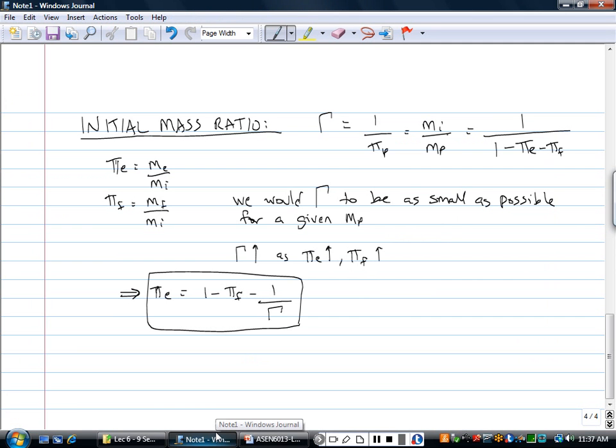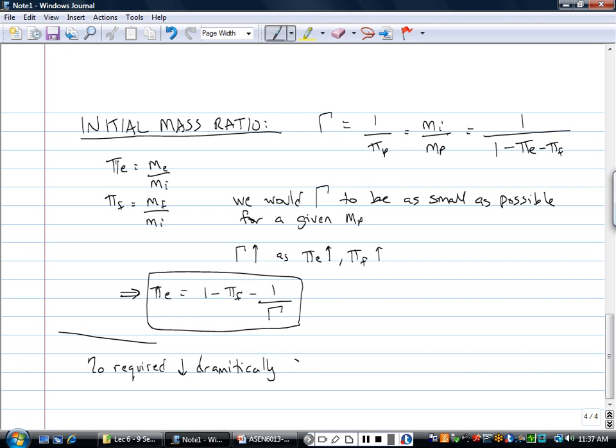So what do we see here? Let's make a note on that one. For the overall efficiency required, based on those charts, what we're really seeing is that this is going to drop dramatically for a change in fuel. The curves showed that very clearly, but it's just driven by the change in fuel. So hydrogen is a clear winner, and of course lowering our empty mass fraction, which really just means more room for fuel.